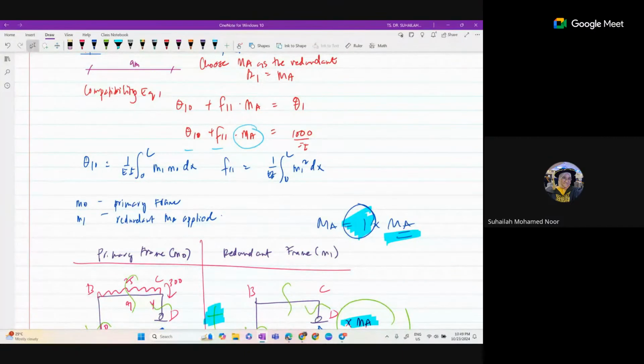When there is displacement, it will affect the performance, the strength, the displacement, everything, including the reaction. So you have to know whenever support displacement or support settlement occurs what happens to the reaction, for example to the moment. You can make a comparison: if it equals 0, what is the moment value? See whether it is smaller or bigger. Sometimes in the exam we ask for that comparison.